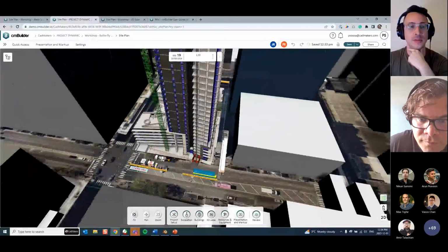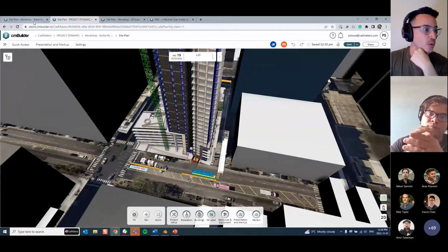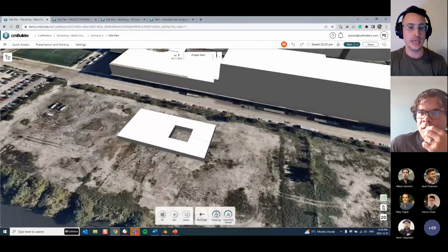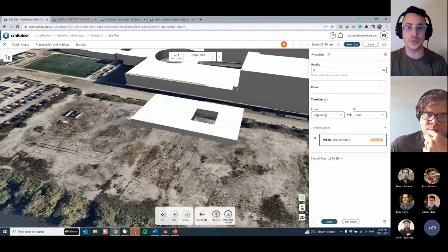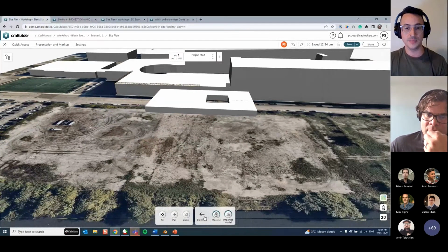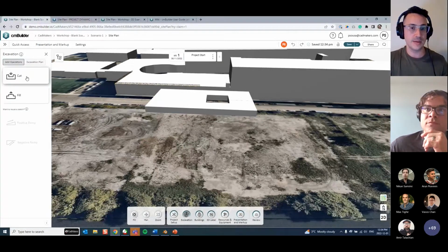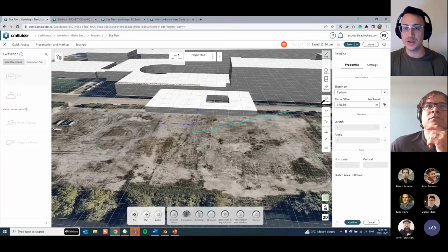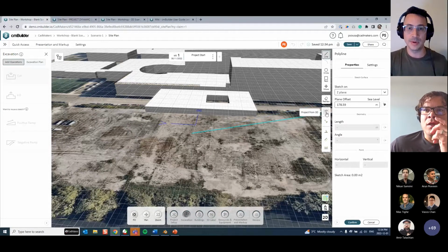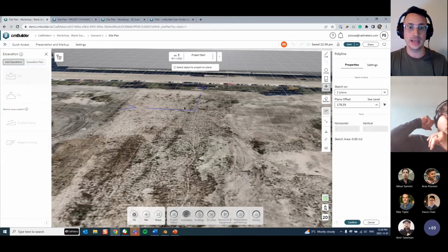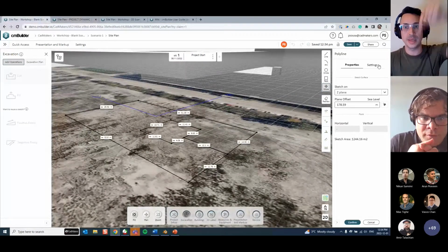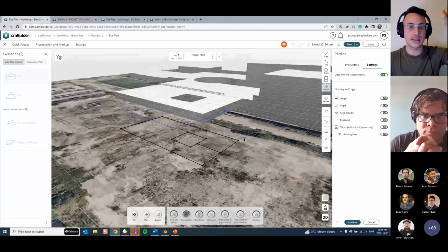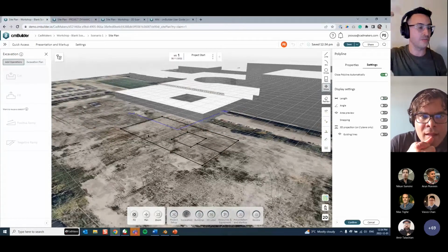So that's a practical way that might help you work a bit more efficiently. Yes. I just noticed that there's one thing I forgot to mention about sketching, which is the projection of an object into the sketch. I'm going to go back over here and create an excavation step and place this excavation over here. I'm going to click on project from 3D, this little button over here. And from this, I can select a shape. I just selected this shape over here, and that shape is going to be cast down so I can do an excavation from that shape, right?